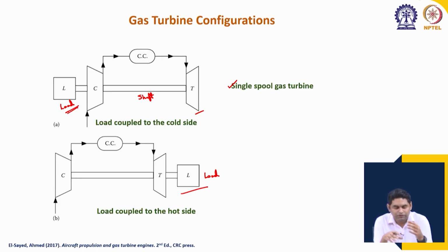If all the turbine stages are mounted on the same shaft, the turbine blades also rotate at the same rotational speed. While this is fine for the smaller blades, for the longer blades the centrifugal stresses become too large, and that can be a problem. So, we have to reduce the rotational speed, which will come at the cost of performance.